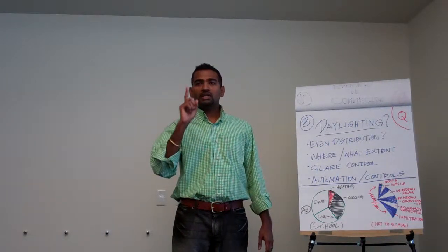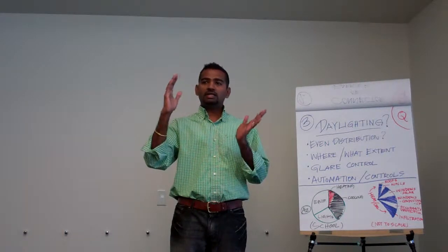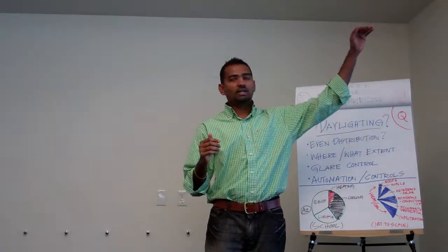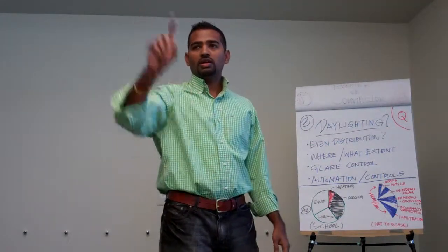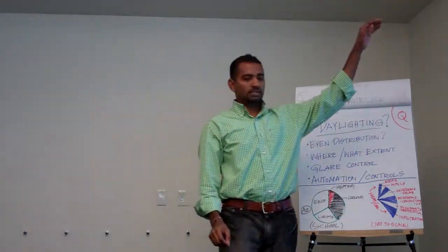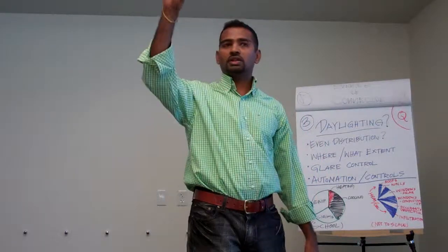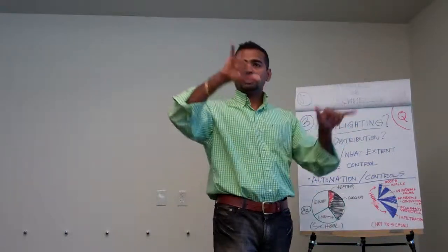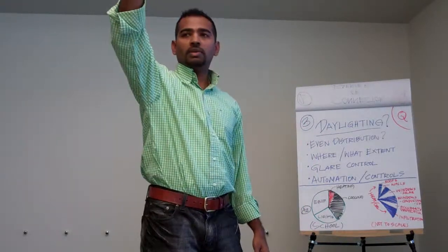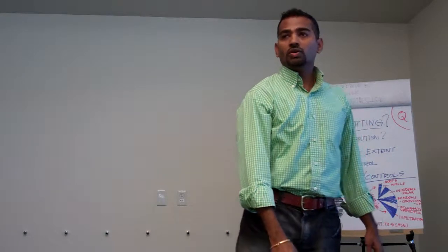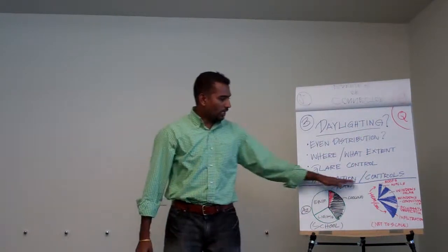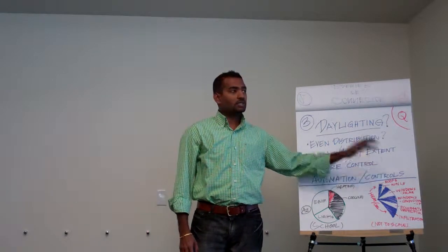The ideal situation is when the sun provides enough foot candles on your table, you want to turn this on. The not so ideal situation is when the sun is still providing 30 foot candles and this is still on, right? Best case, worst case. So if you don't have an automatic control, you still have to worry about the radiation due to the 30 foot candles that you're doing, right? So if you don't want automation and controls, then your strategy should be different.